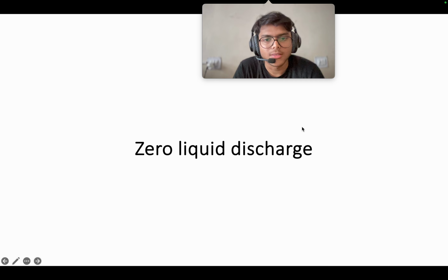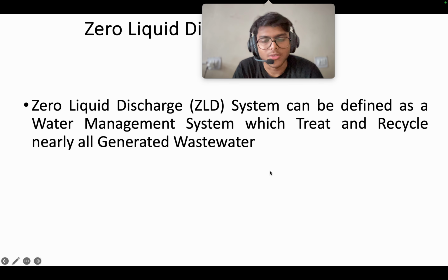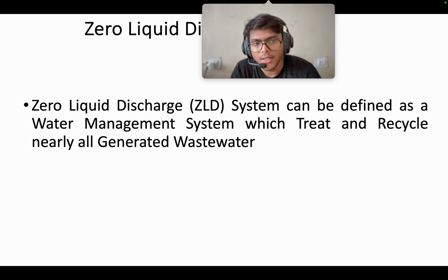So, what is zero liquid discharge system? That would be the first question you would have. Zero liquid discharge system can be defined as a wastewater management system which treats and recycles nearly all wastewater generated, right? All the wastewater generated in industries or any other sector, it will treat and recycle it for further use, right?